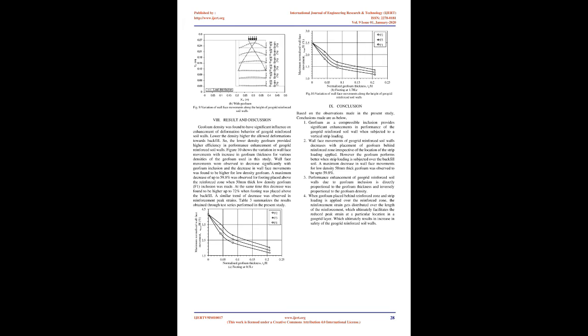It can be clearly observed that for the geogrid reinforced soil wall without geofoam inclusion, the majority of the deformations are occurring towards the face of the geogrid reinforced soil wall. A top portion of the soil exactly behind the reinforced zone was also observed to shift upward, confirming Terzaghi's conventional general shear failure theory of shallow foundations.